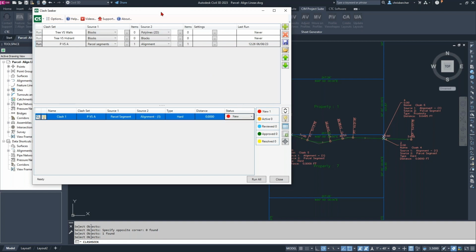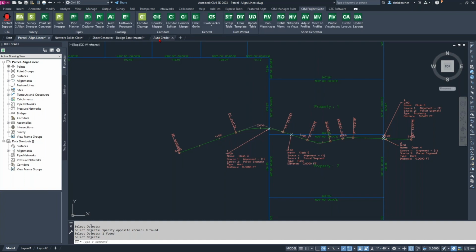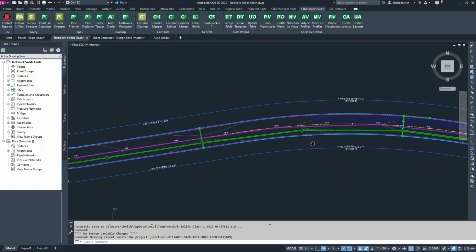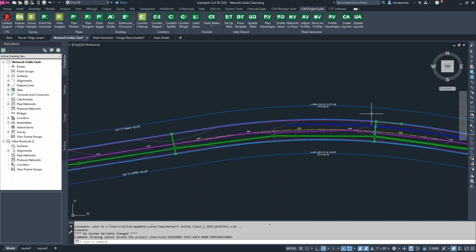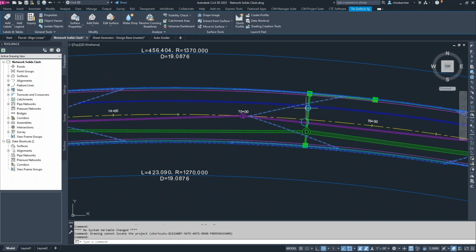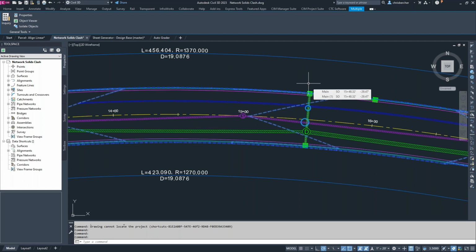A couple more things I want to show you real quick, and I'm going to switch on over to one more drawing, I think. Well, I'll take that back. I got 2 more. I want to show you the pipe one again because that's kind of an important clash. So in this case, one of the things that will need to be clashed, or that you'll want to use this on, is, in this case, we've got pipes interfering with whatever this solid object is here, and I think the intention here was that it was going to be a soil boring, and it fell. They're interfering with some of the underground pipe objects that we've got here.